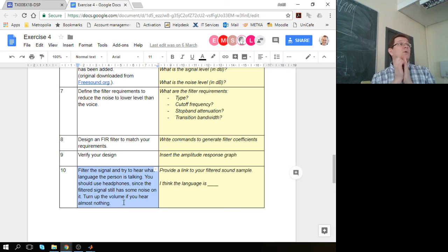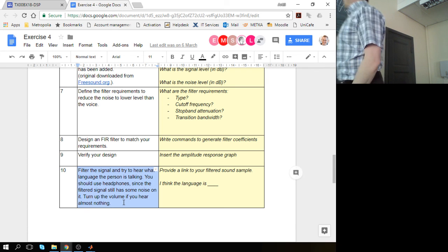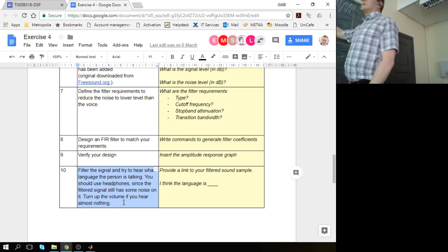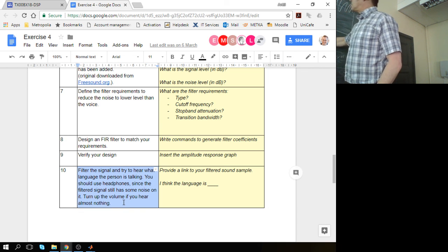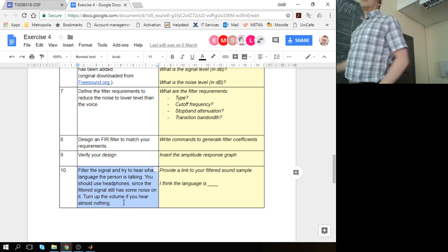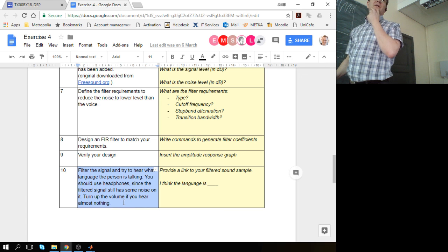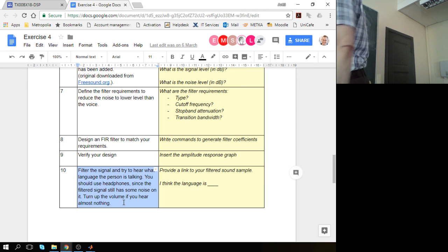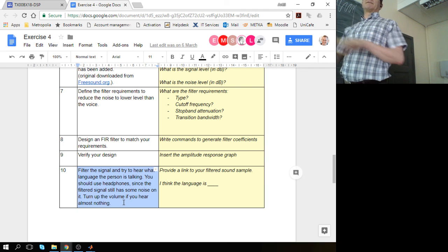One small hint: usually when you start the filter with a time-based signal, you might get some extra bang at the beginning. You can either apply a time-based window to get rid of that bang, or just leave it there, turn up the volume and let the amplifier saturate.